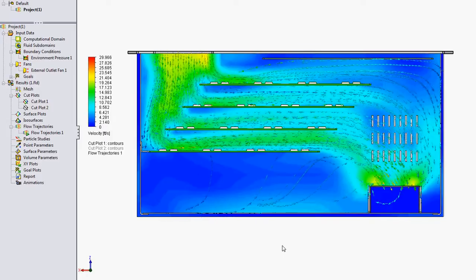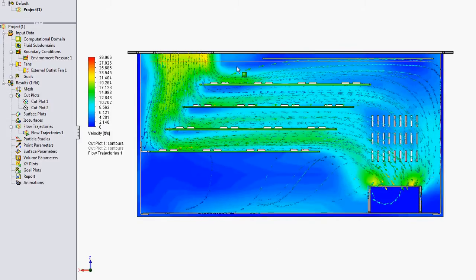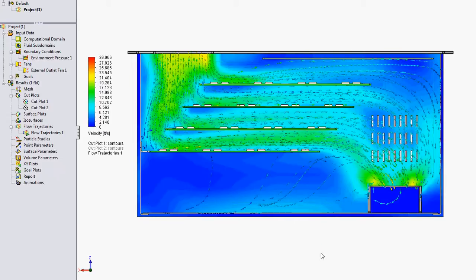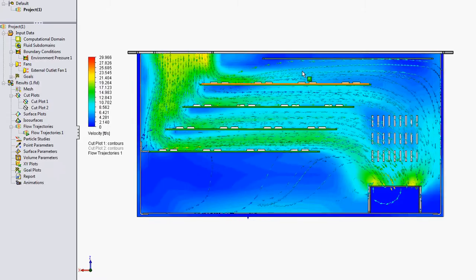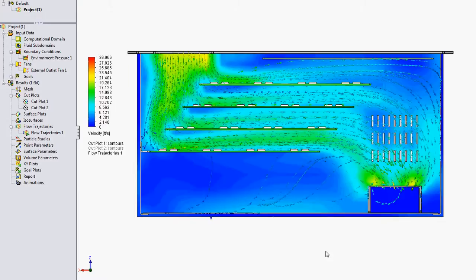So for this, I would look at the worst case card, probably this one here, and use that flow. And as long as we've got even power loading on these, and I'm meeting my junction temperature derating requirements on this one, I feel pretty confident there.